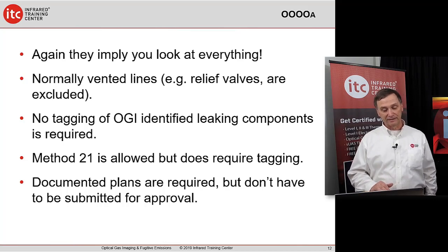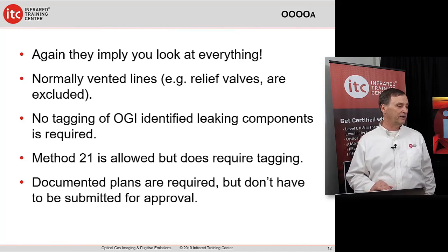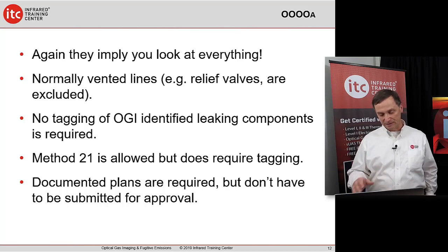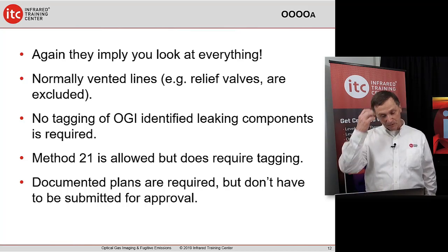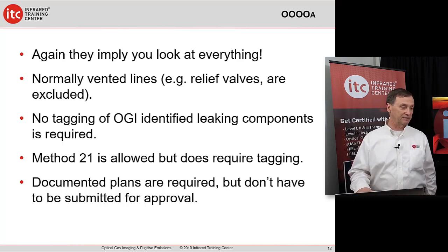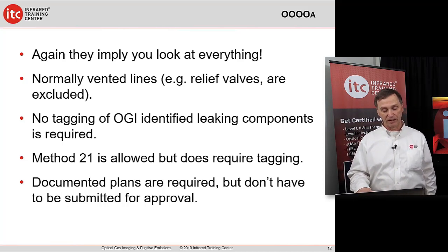No tagging of the components is required. So when you find it with an OGI, you document it with a picture, GPS, time, date, etc. But it does not require tagging of the component. Method 21 does. And you have to have a very detailed documented plan.